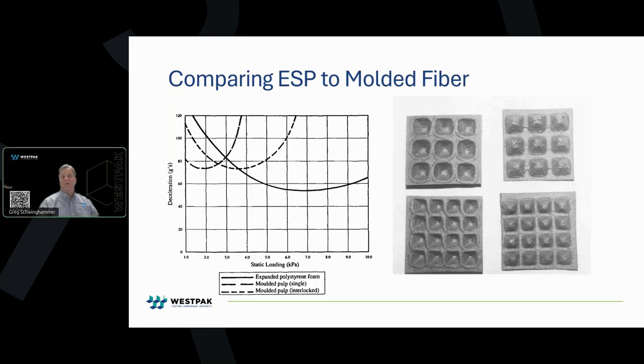If we use our product from slide 9, which had a critical acceleration, it was one slide ago. Does anybody remember what that critical acceleration was? That's right, again, 80 Gs. Any of these materials, when properly loaded, would protect the product from impacts of 36 inches. So you can see on this graph, it's the 2 molded pulp cushions pictured here on the right. And in the belly of the curve, they're both below that 80 G deceleration level. And the EPS, if you had to load it out higher, is already below that as well.